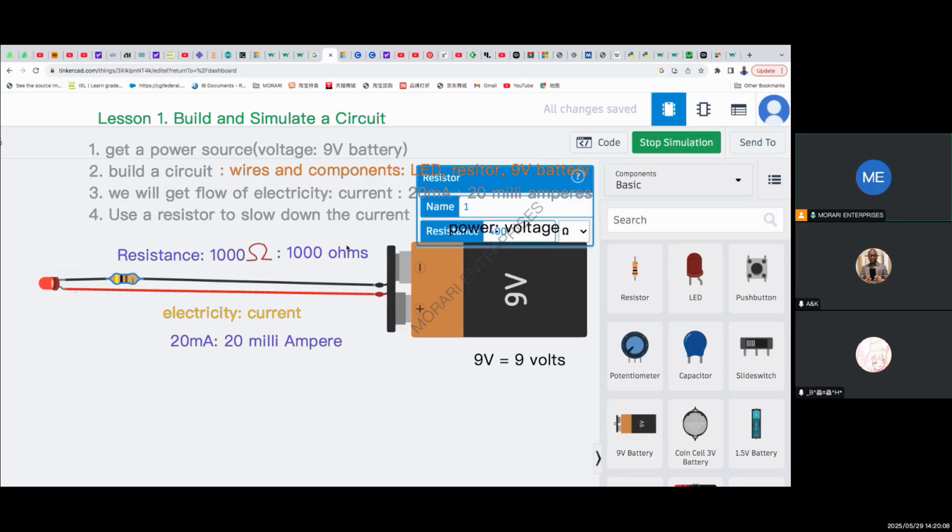But make sure that you don't have any warning. If we go down to 400, it's brighter. So the resistance should not be very, very high. Now, if we take the resistance to like 4,000, you see, it's very dim. We come back to 400, it's brighter. You go to 4,000, it's dim. You go to 40,000, it's not working. It's off. 4,000, a little dimmer, and 400, very good. So more resistance, not good. 0 resistance, not good. Just the right amount of resistance.